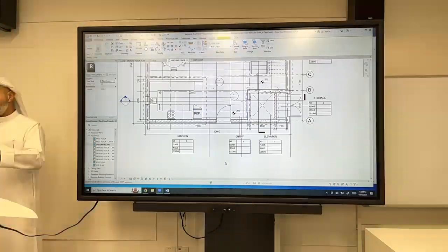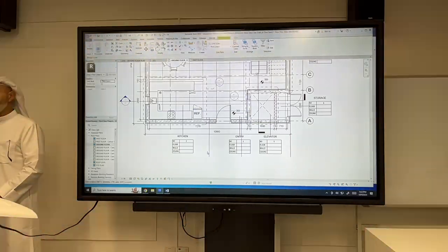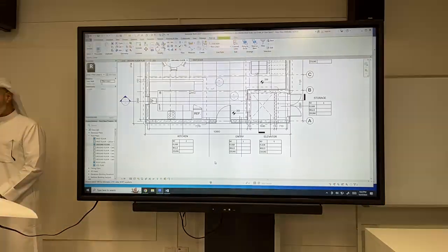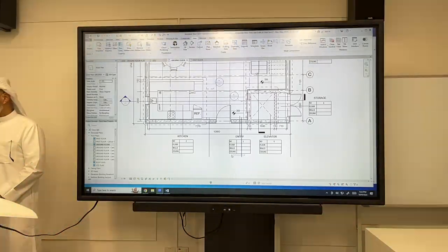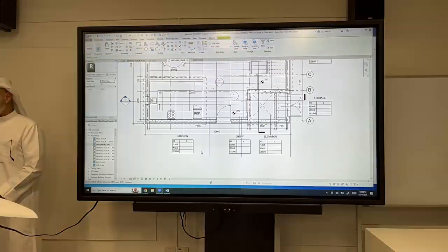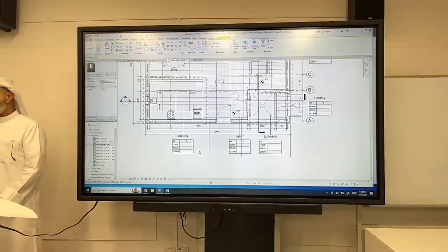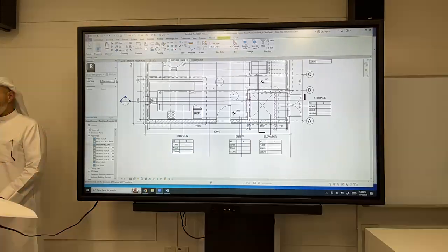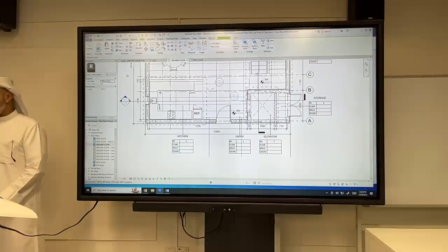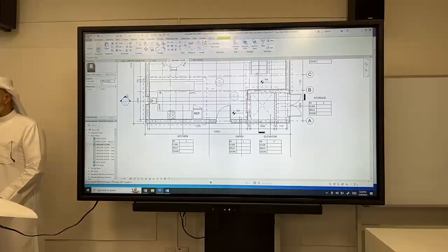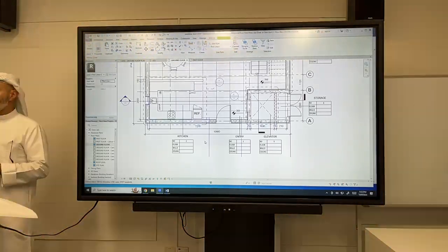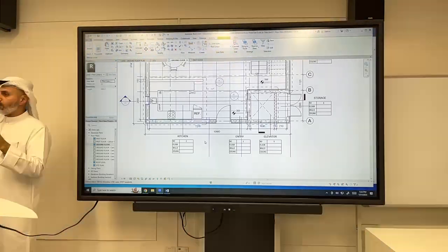Copy or paste. Exactly. So select your two lines that you split the walls on. Copy them. Control C. Control C, move, CO. What's the difference? It gives you different options. Copy means CO, usually you're copying within the same view. Control C you can take from file to file or view to view.